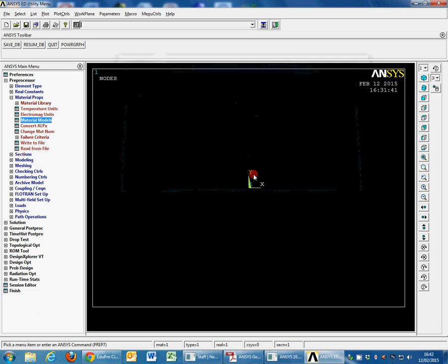Okay. So now we're down to modelling this thing. Now, beam elements don't suffer from what we call mesh refinement. So in theory, I could model 1, 2, 3 beam elements for each of the spans. But having said that, for plotting things like bending moment diagrams and outputting various moment results along spans, it's best to have a few nodes along a beam for those purposes.